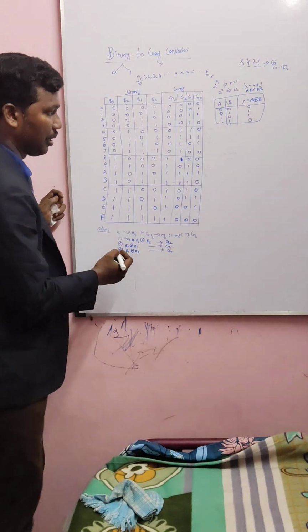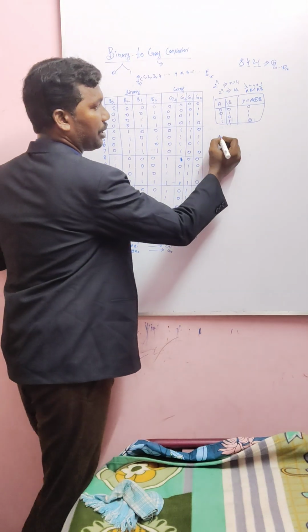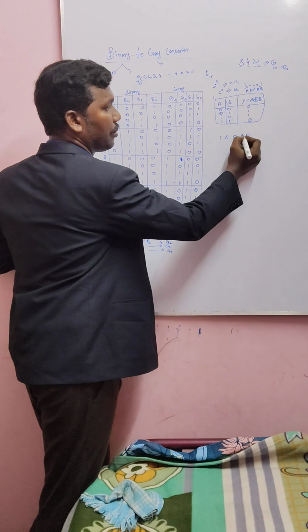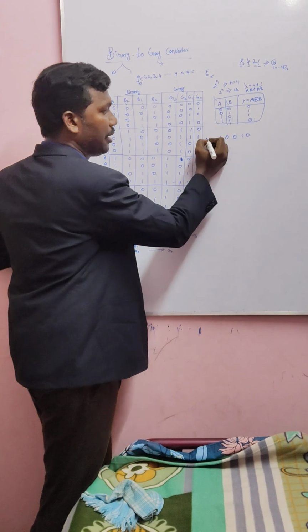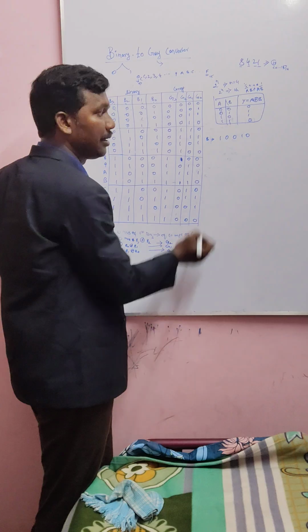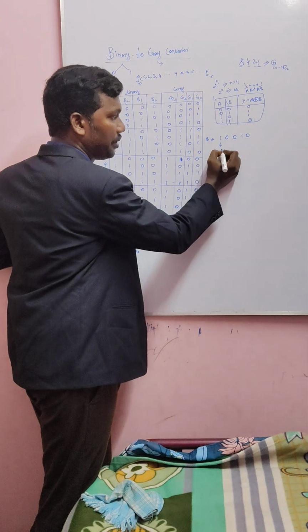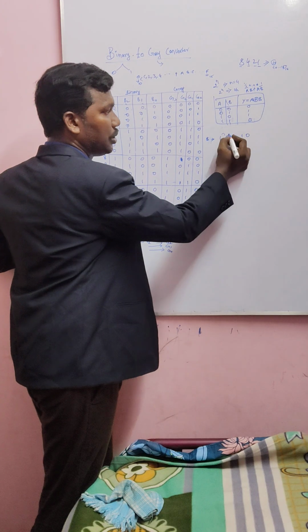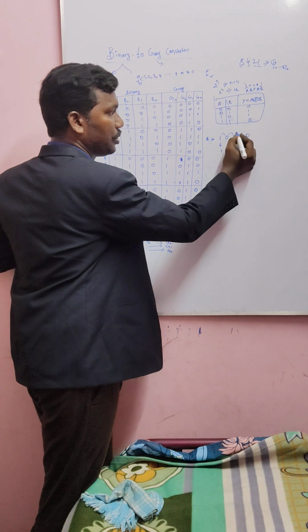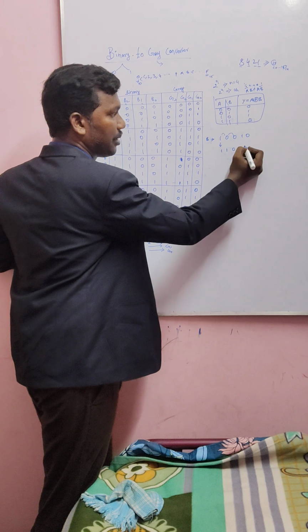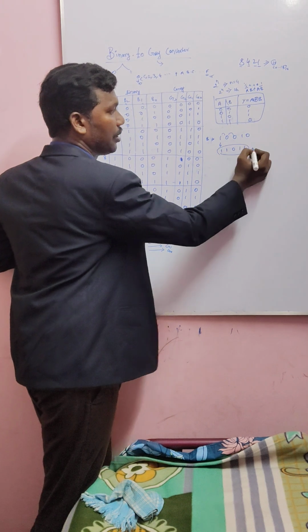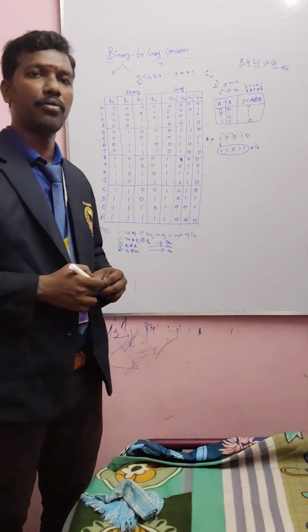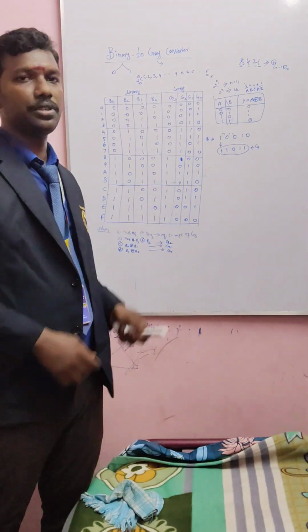If you want to learn clearly, I'm taking one example, 1, 0, 0, 1, 0. If I'm moving to 5-bit, this is a binary representation. What is the equivalent gray? So you all know that the MSB will be the same, and the next bit is 1. Do XOR of this, 0. Do XOR of this, 1. Do XOR of this, 1. So this is a gray code, right? So for any numbers, 3-bit, 4-bit, 5-bit, whatever, up to 2 power n, this is the procedure to convert it.